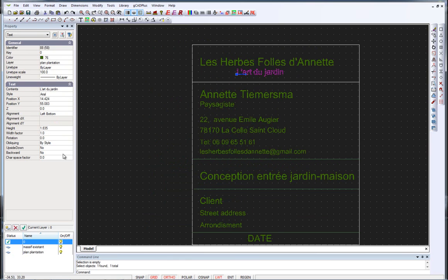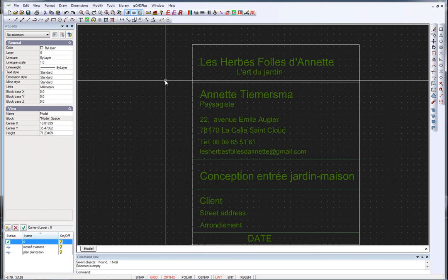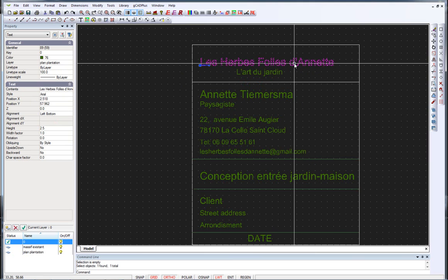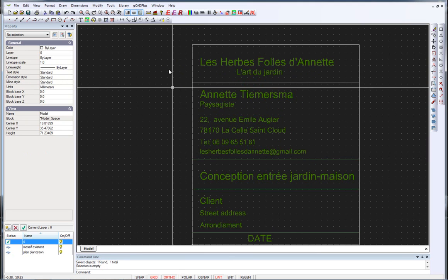Let's pick this one, 1.8. So most drafting standards will say text on your drawing sheets 2.5. The next height down would be 1.8. So let's make that 1.8. So we normally go 7.0, 5.0, 3.5. This one here, which we've set at 2.5 and then down to 1.8.